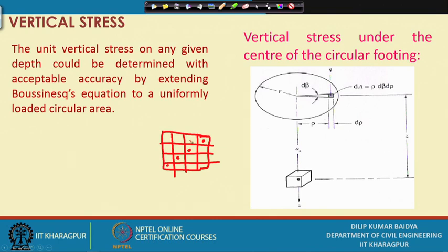To do this, the unit vertical stress at any given depth can be determined with acceptable accuracy by extending Boussinesq's equation to a uniformly loaded circular area.